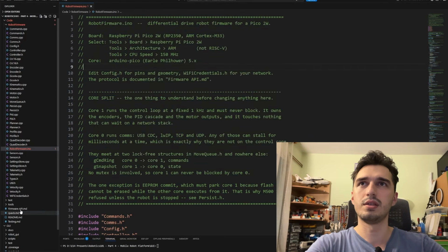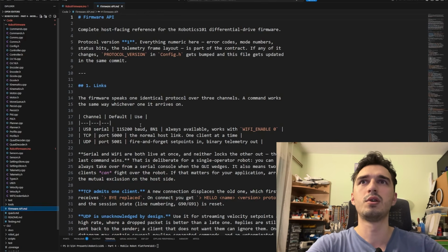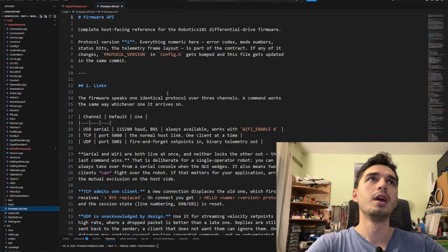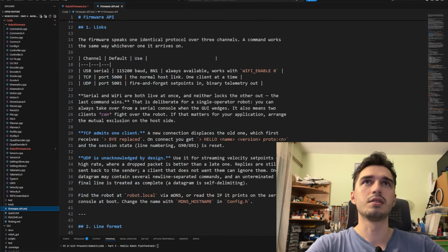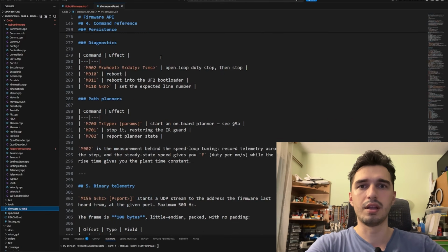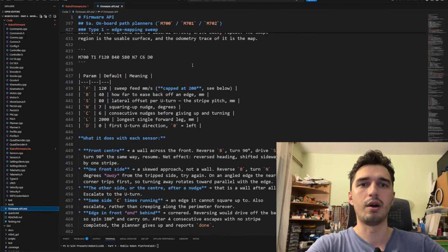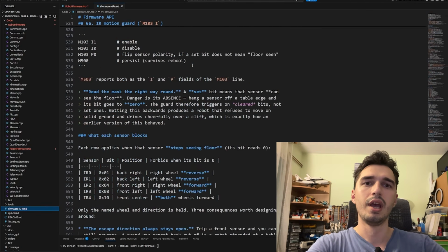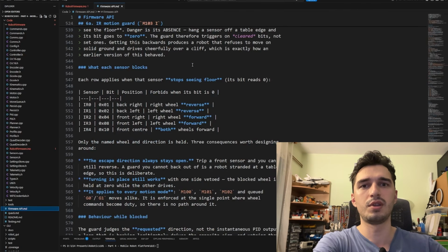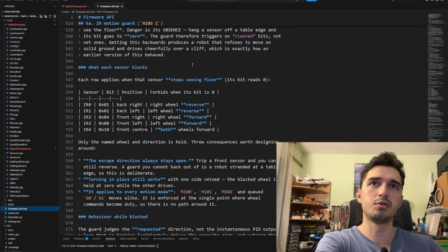One thing I always do is things like this. Since we have two pieces of software that need to communicate, the firmware and the graphical user interface, I make sure that the session doing the firmware creates something I'm calling the firmware API MD, or a README file, and this is literally the documentation on how to communicate with the firmware. Like in the robotic arm project, this is just G-code style commands, but it literally gives it the whole recipe, the whole cookbook of how every command needs to be configured. Then when I'm doing stuff in the graphical user interface thread, all I do is tell it to always look at this file because it has all of the latest updates,